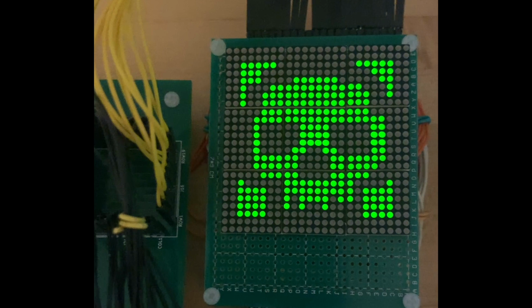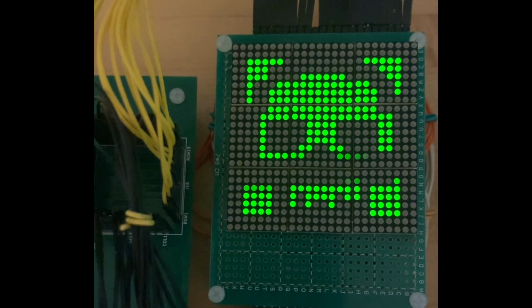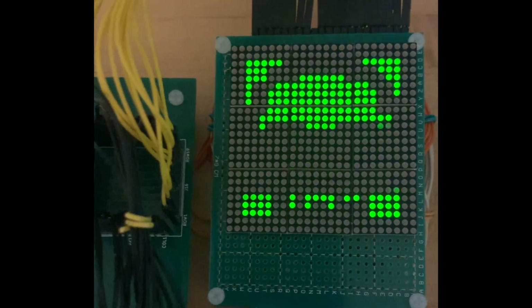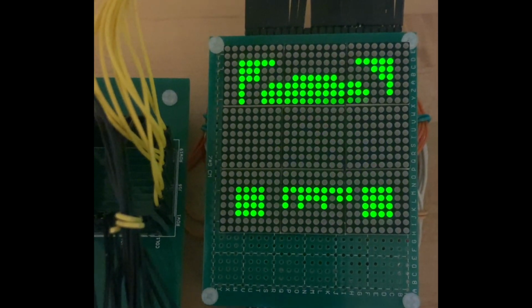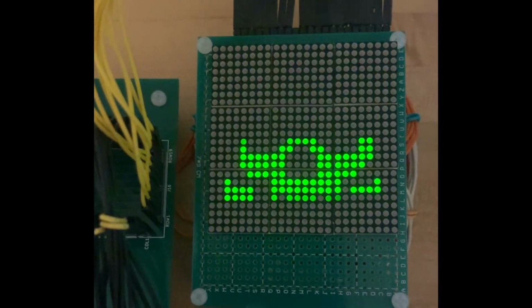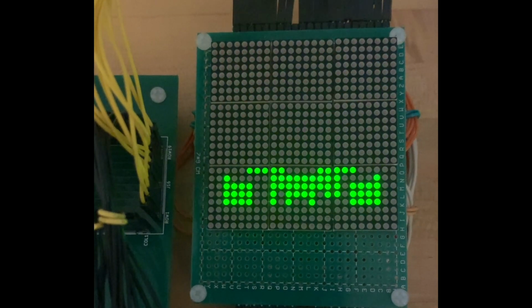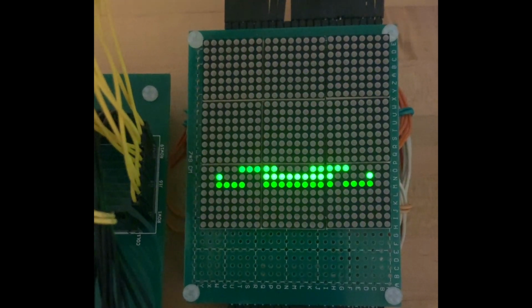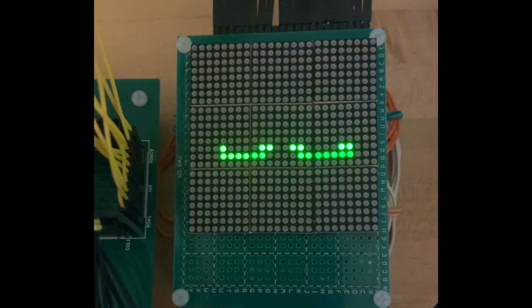Usually, the display is clocked at a high enough rate such that it appears to show a constant image, even though only one row of the display is actually illuminated at any given time. As the clock rate is decreased, the image starts to shimmer, and eventually the scanning is slow enough that the camera filming it can begin to pick up groups of rows and then individual rows lighting up. Further decreasing the clock frequency makes this effect even more apparent. Finally, we can see how the chip is scanning through the display, enabling only one row at a time.